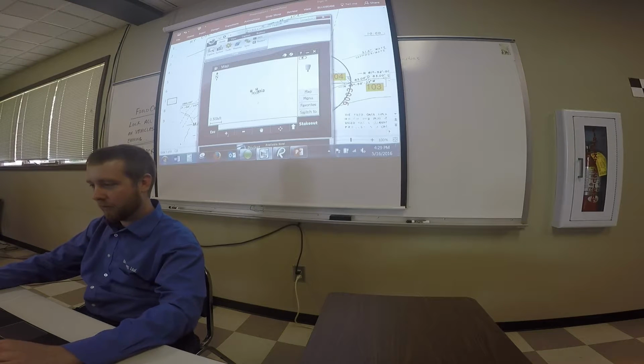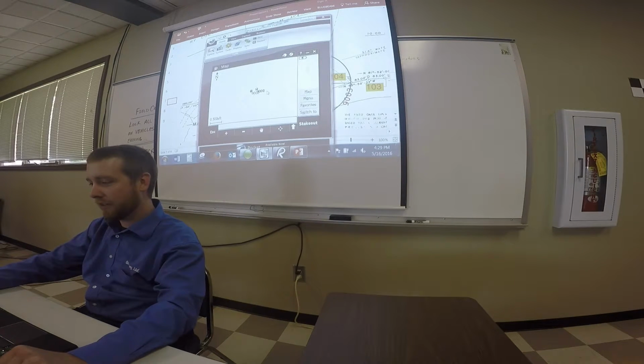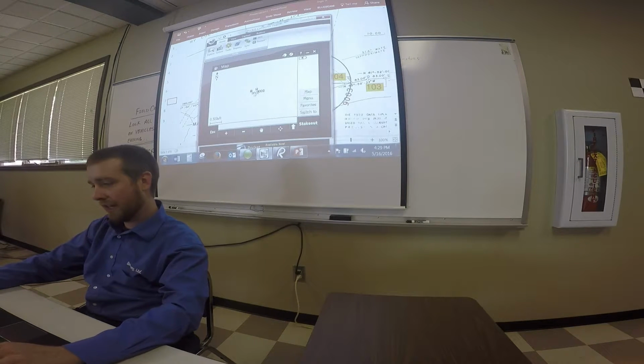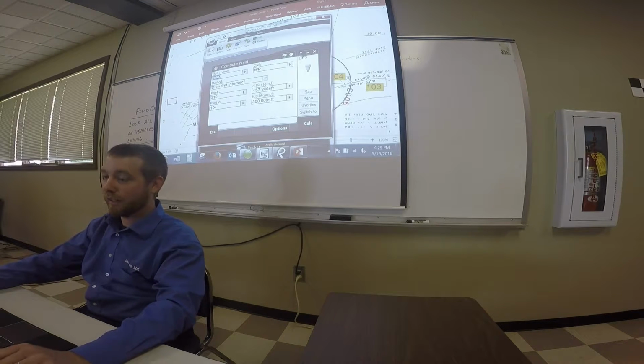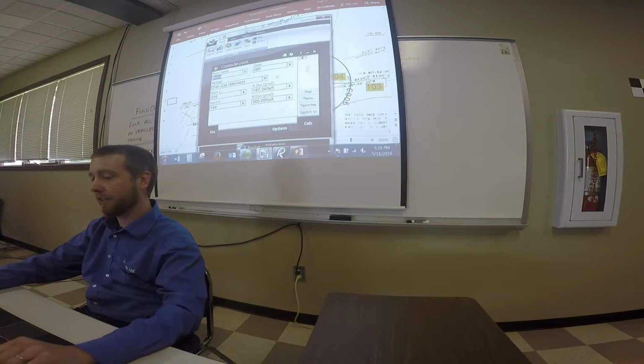Yeah. Now you see, oh, I hit the wrong button. Hold on. Okay, now you see how 9000, 9001 are right here? That's because the turned angle is going to be more accurate and take into account the differences in pins, because not every pin is going to be exactly where it's supposed to be, especially the older surveys. 9002 got it about 2/10 away, going off those distances, but that'd be plenty close enough to help you find the pin to wander around and then figure out if you need to set it or not.